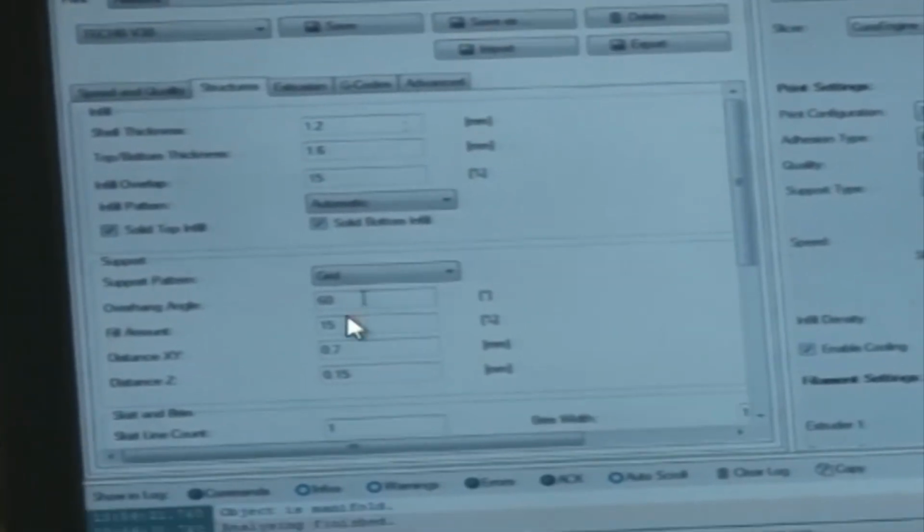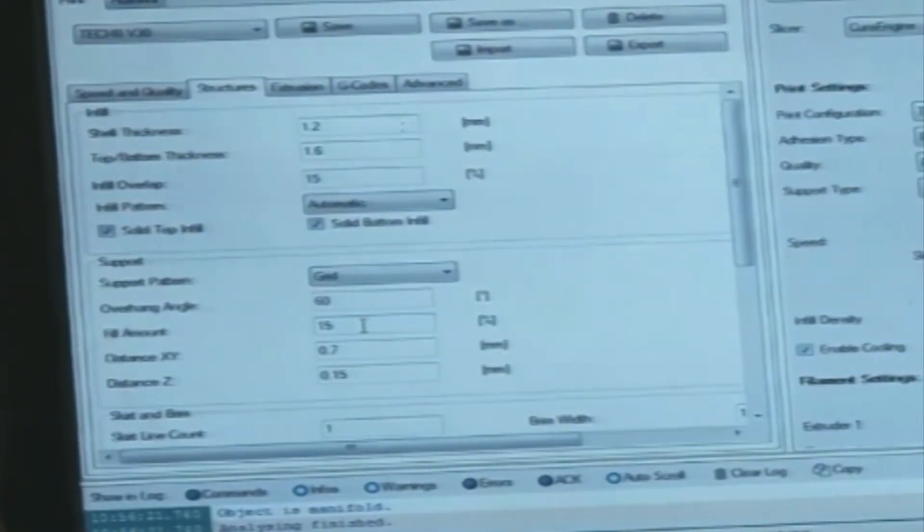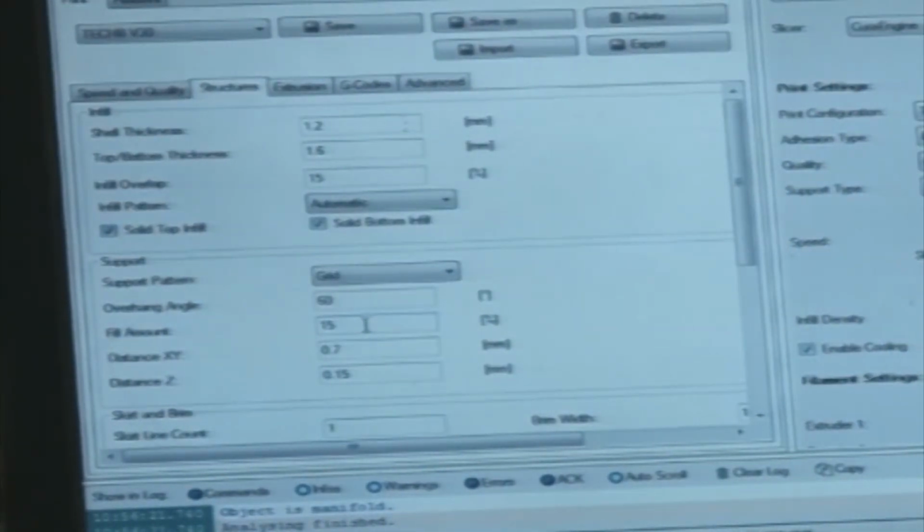Okay. So the overhang angle is 60 degrees here. This overhang angle is for this machinery. If we are going to deposit, or print or manufacture any job, if it is solid, there is no issue at all. If it is a conical shape, an angle is up to 60 degrees.